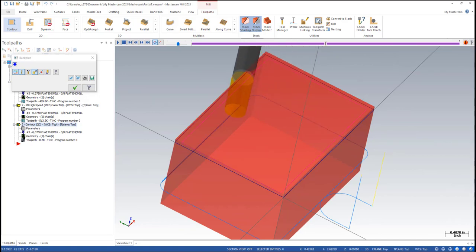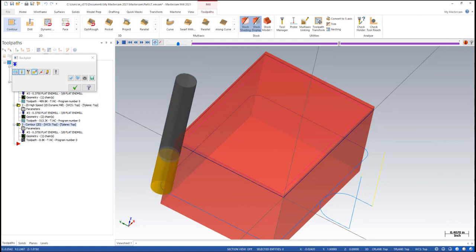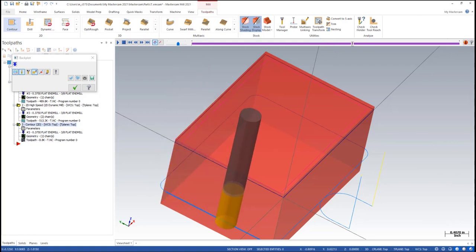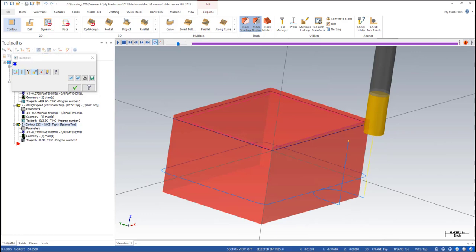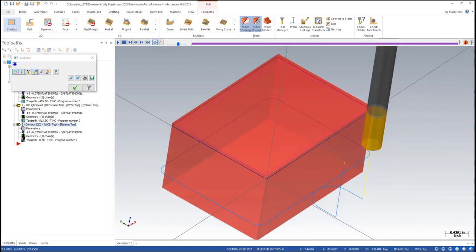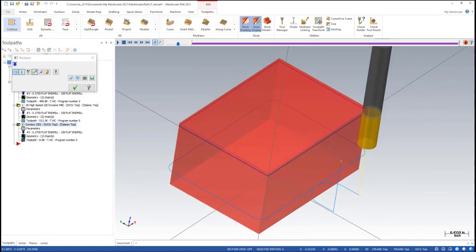It's conventional milling. So the tool is always rotating in a clockwise method, but rather than climbing through the material, it's conventional milling. So it's sort of ramping into the material, which we don't want. It tends to lead to chatter, and we don't get a radial chip thinning effect, and it increases tool wear. So try to avoid that.